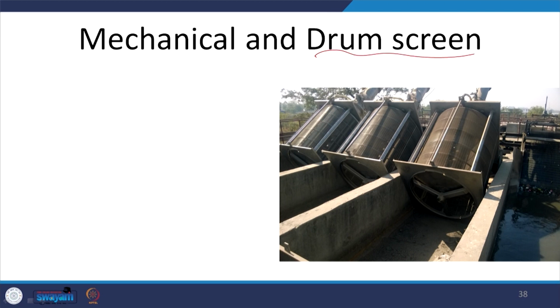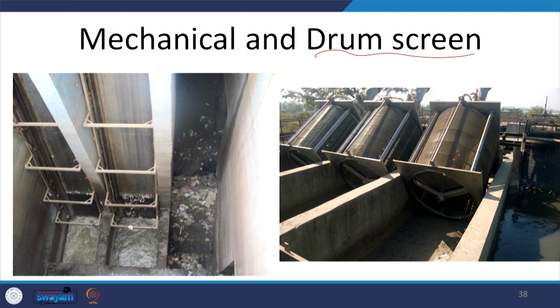Here we are looking at relatively finer particles, depending on the size of the pores in this screen. But as I mentioned, in wastewater plants people typically do not go for that, though depending on the waste or your design, you might want to. The issue is that the maintenance is high. But again, mechanical screens, front end and manual, are what we have here.